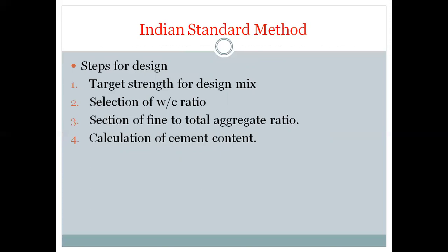Next step is selection of the water cement ratio. Depending upon the requirement of the strength grading of the concrete, we can select the water cement ratio. Also there are standard graphs available which will be useful for following the mix design steps regarding the concrete. So we have to use the standard graphs for the design.